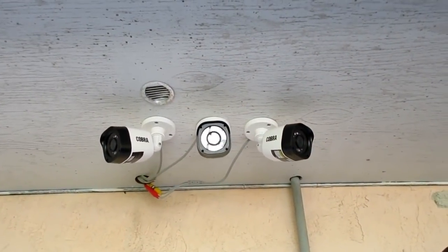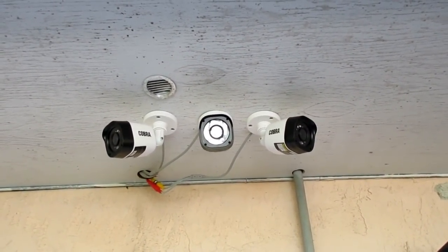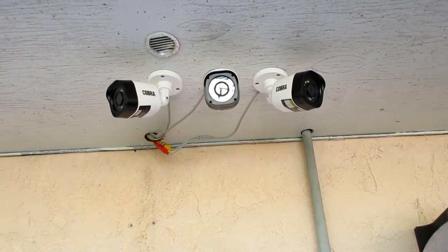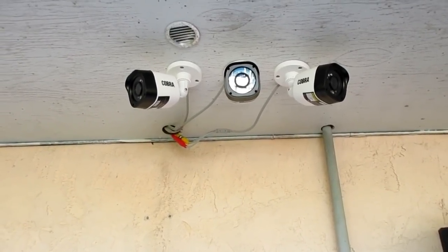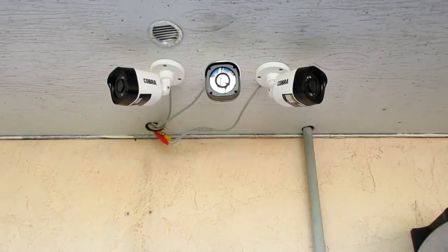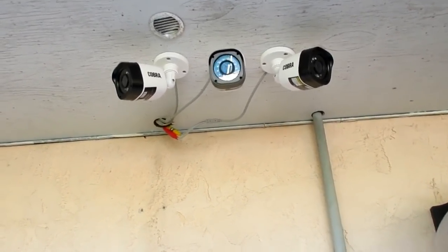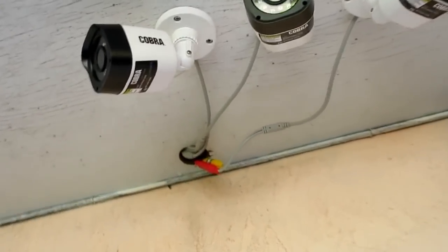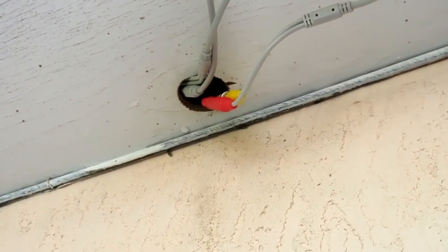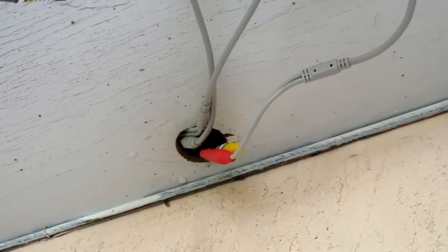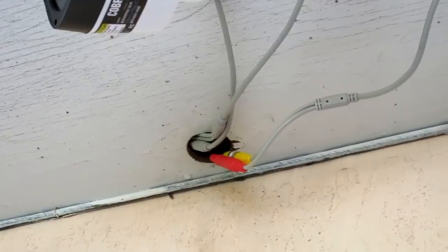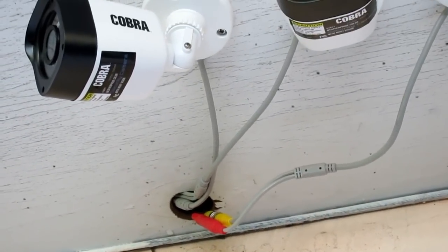So again, here's my 3 cameras here in the backyard of my house. I've mounted these all up here, and with the 3 of them, I can see the center of the yard, and the left and the right of the yard, so it pretty much covers the whole house. Now, when I wired these up, I happened to have this hole here in the house, and that's where I ran my wires through. There's a better, neater way to do it. The proper way to set it up is to drill a hole right underneath it and run your wires straight up, so they wouldn't be seen that way.